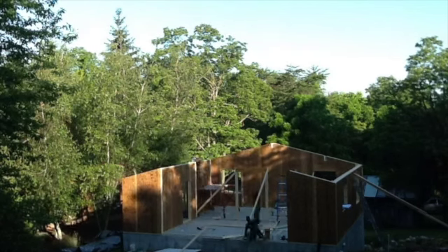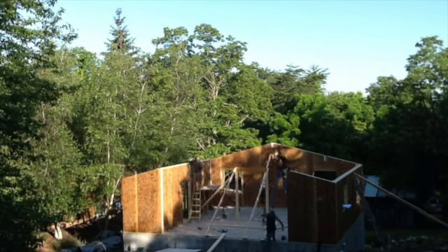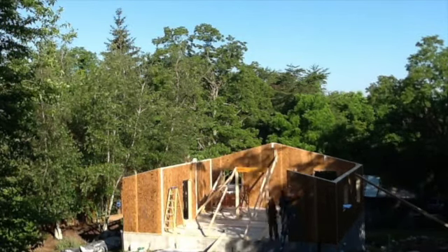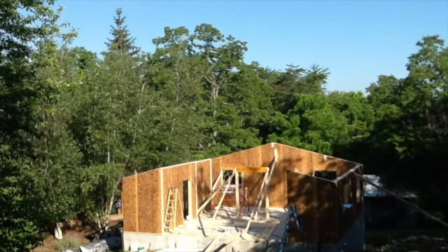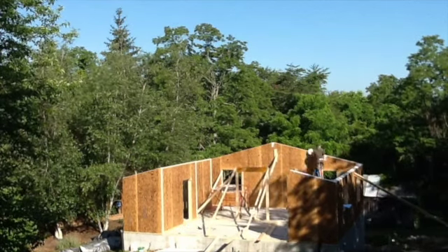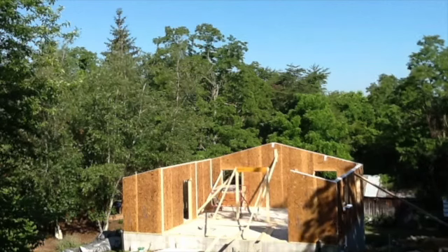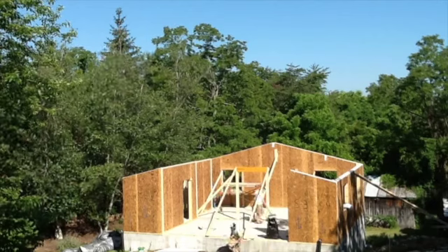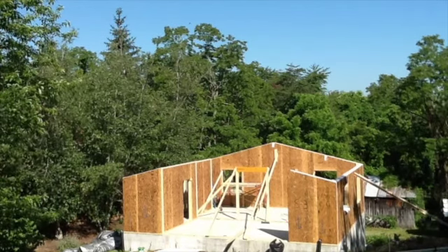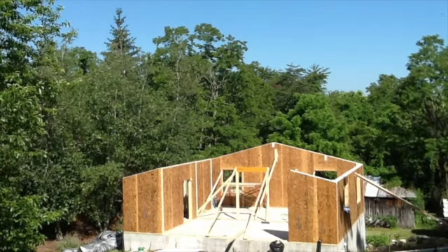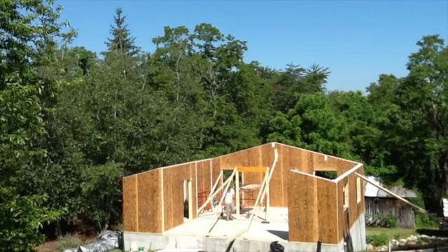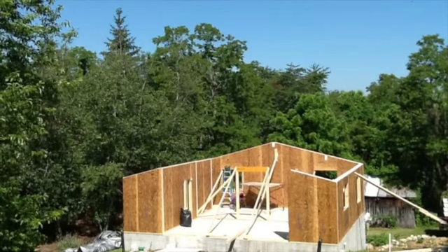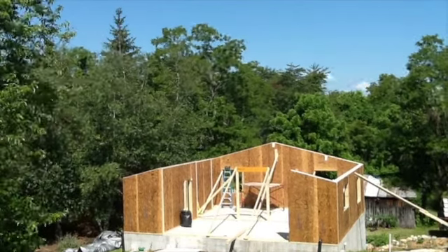Now here we are on the 4th day of construction, and what they're doing is constructing a center structural support wall that will support the parallam beams that go into those pockets you can see in the wall furthest away from the camera. So there are beams at the midpoint of each of the roof spans, and ultimately this building has a cathedral ceiling, so it's entirely conditioned space inside that envelope, which is one of the biggest benefits of SIPs, that you're able to recover a lot of usable space within the building.